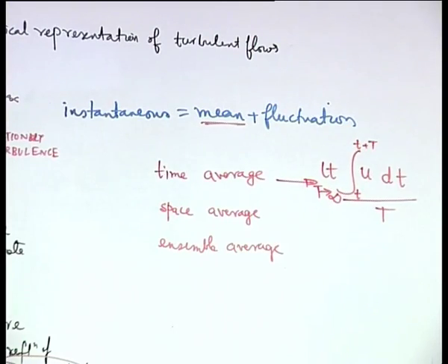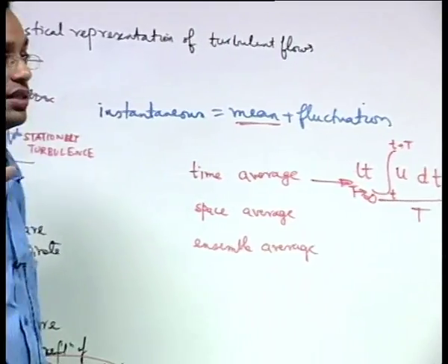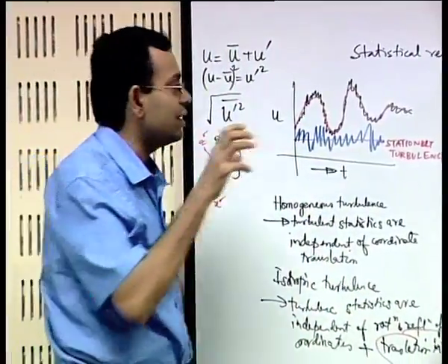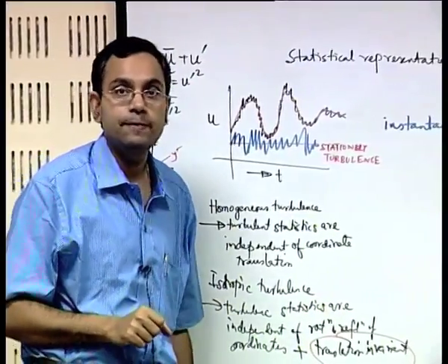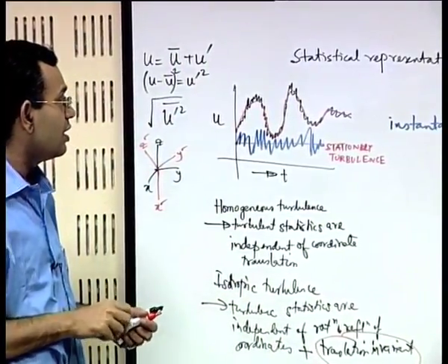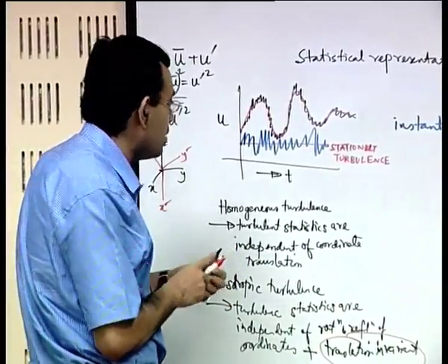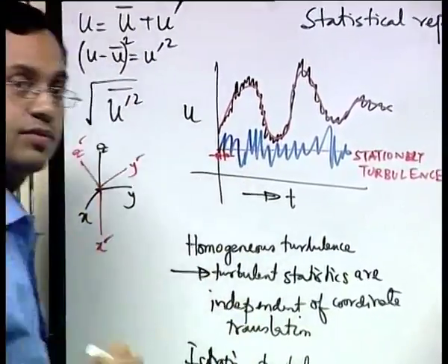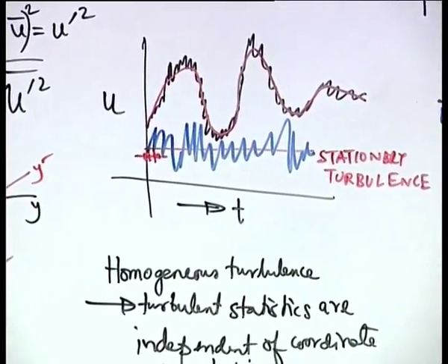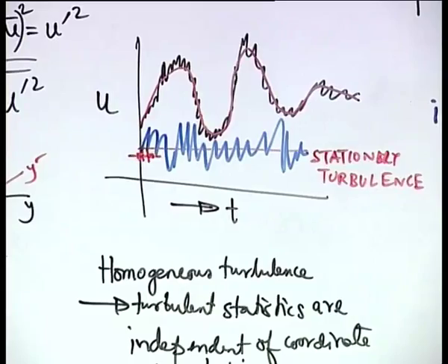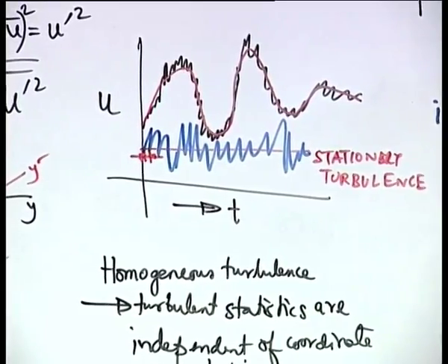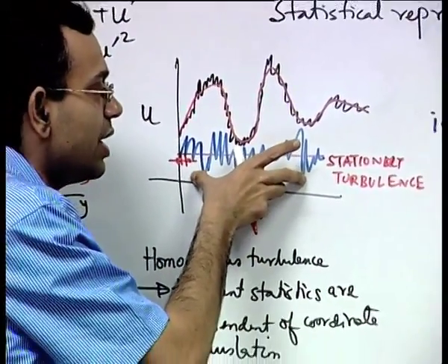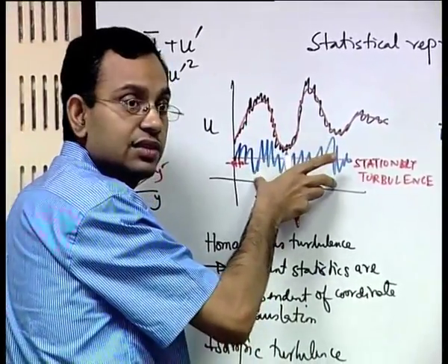So, now let us consider the issue of wide range of time scales. We had earlier discussed the issue of length scales. Now, let us focus on the issue of time scales. In a turbulent flow there are turbulent fluctuation time scales, and these are very small time scales over which the turbulent quantity fluctuates. On the other hand, there is a system time scale. You can see that with respect to the system it does not change on an average.